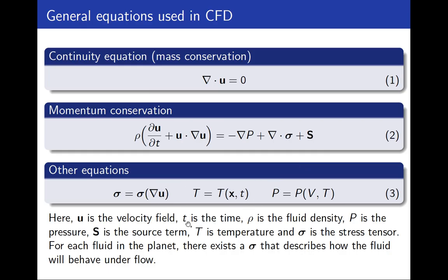And then we might need additional equations, depending on the problem. So for instance, if we are interested in simulating a polymer, chocolate, volcanic lava, air, we actually need a constitutive equation, an equation that relates the stresses, the forces that are applied over the fluid, which can cause deformations over the fluid material. So we need to specify this equation here. It is different for every fluid in the world.